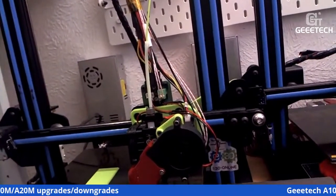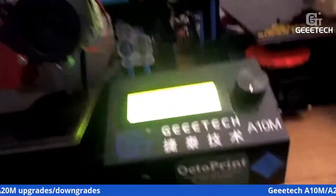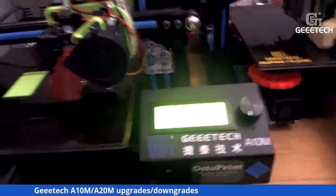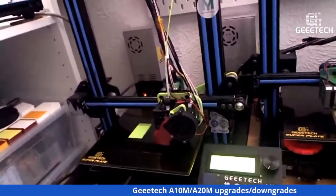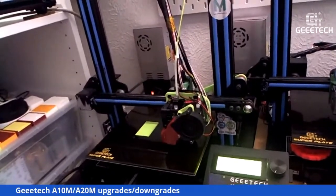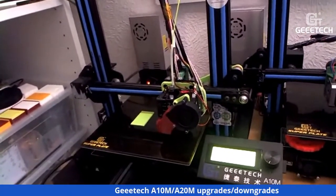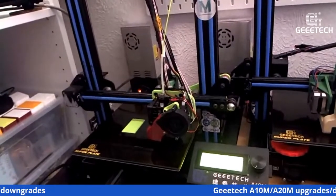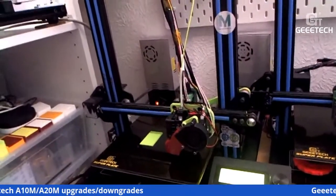What can I also tell you? Yes, that's very important, the firmware. Most of the machines come with Marlin firmware. I think they come from the factory with Marlin 1.1.8, yes. And I also upgraded the firmware to Marlin 2.0, because the newer Marlins have much more features, and some of the features improve the printing quality or the printing itself, the easiness.